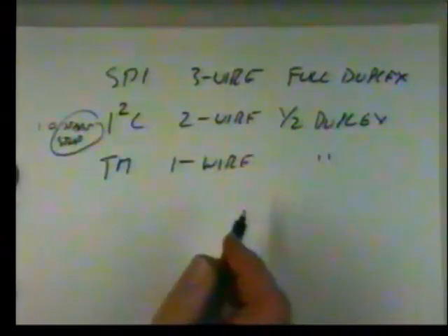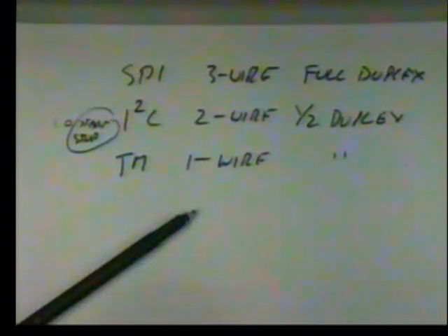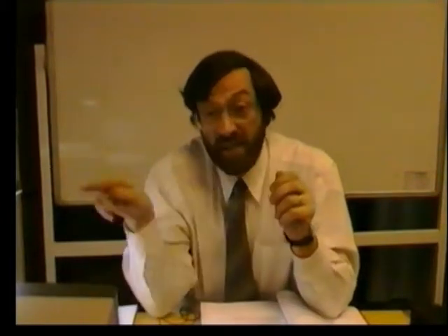And that start and stop bit gave us the ability to frame our transactions, to resynchronize the bytes. And every byte transfer, whatever the direction it went in, was followed by an acknowledgement. You always had an acknowledgement. The last bit, the least significant bit, told us whether the next transfer was forward or back.